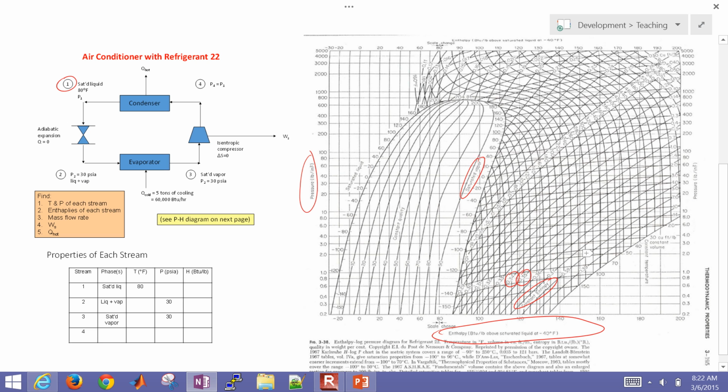And then we have saturated vapor, saturated liquid, and then there's like 50% quality, so 50% weight percent vapor or liquid. Okay, and then we have some temperatures right here as well. Those are going to be temperatures in degrees Fahrenheit. So this is going to be the place where it's going to boil, let's say, and then become all saturated vapor. Okay, so let's go ahead and do these calculations, figure out where we are on this chart with